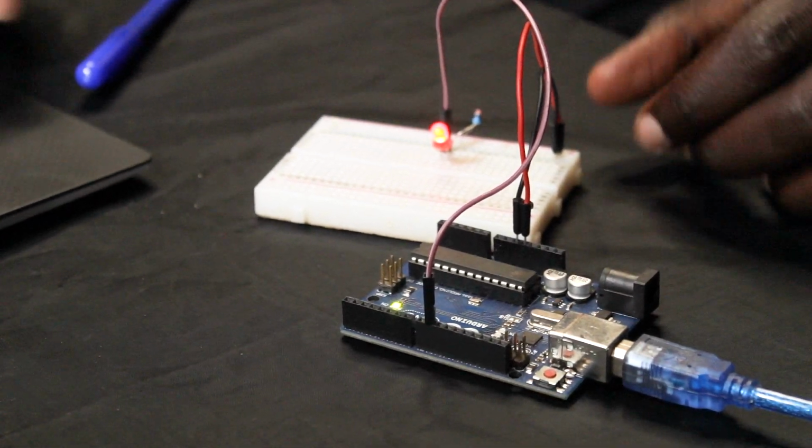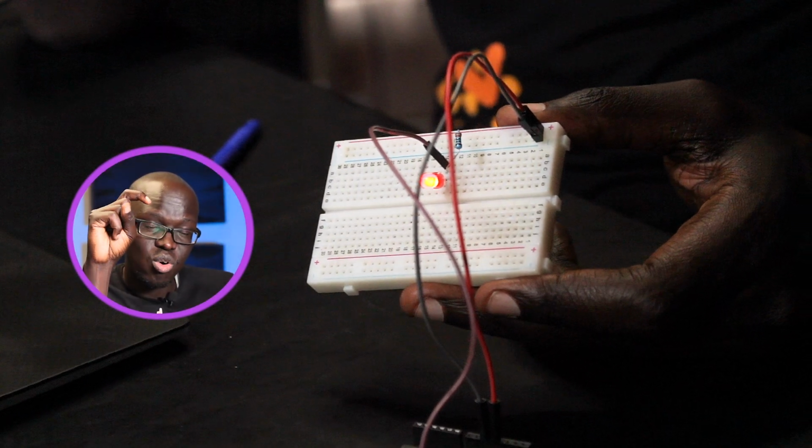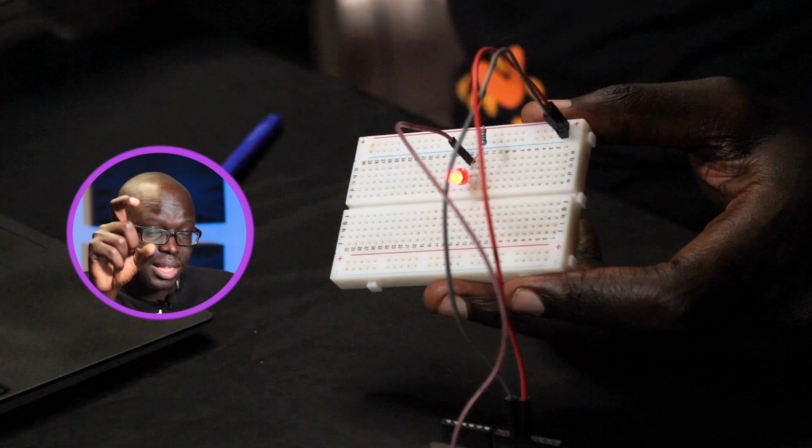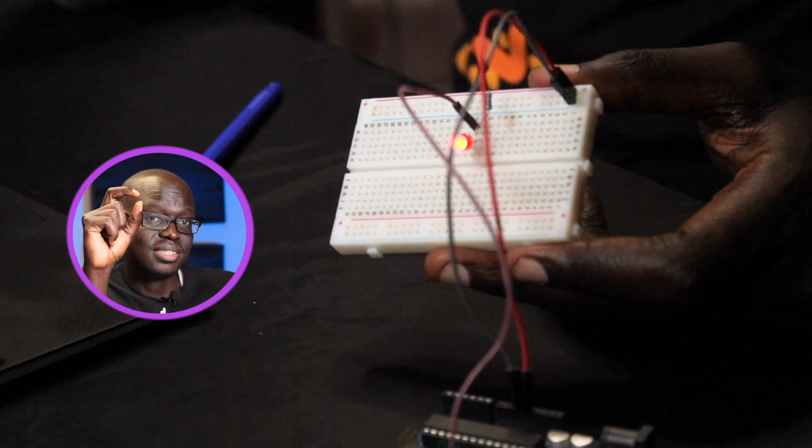And so now we have our LED lighting. But it's receiving an analog signal, meaning that what's happening right now is that the analog pin is sending a really large number of instructions to the LED, telling it to turn on and off in a specific pattern and for a specific amount of time in order to make it look like it has a certain amount of brightness. Because it's sending that signal in a specific pattern, it is creating an average value for the power that the LED is receiving. All right, so let's take a quick look at how PWM works.